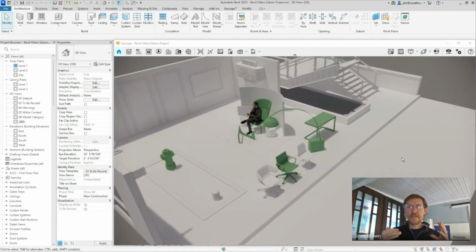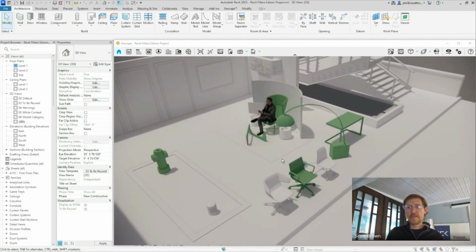Where Revit phasing falls flat a lot of times on big projects for any kind of construction sequencing, or even just healthcare sequencing of phased construction, you'd be able to group elements utilizing a shared parameter and be able to put these filters on to show, okay, phase one includes this whole build out, but how we're actually going to do that is through a bunch of sub phases, right?